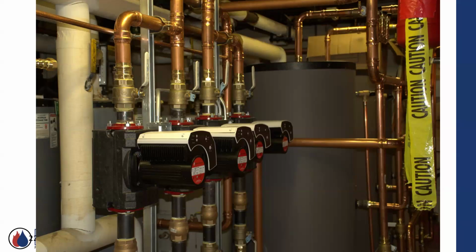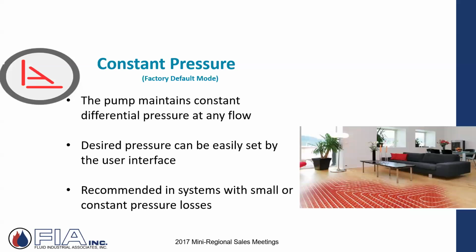In fact, if you just turn around and look real quickly, right there against the wall, there's a cutaway of a tank, so it's showing a coil inside there. So when that pump comes on, it's just taking boiler water and going through that internal coil and back. So it's fixed, but you can dial that pump in to whatever the requirement is from the manufacturer of those indirects. Hey, I need 15 gallons a minute, and I've got 3 coils. Okay, you need 45 gallons a minute. You've got to overcome the pressure to all. And then the other thing is one's going and one's backup, and they can communicate with each other and talk to each other.